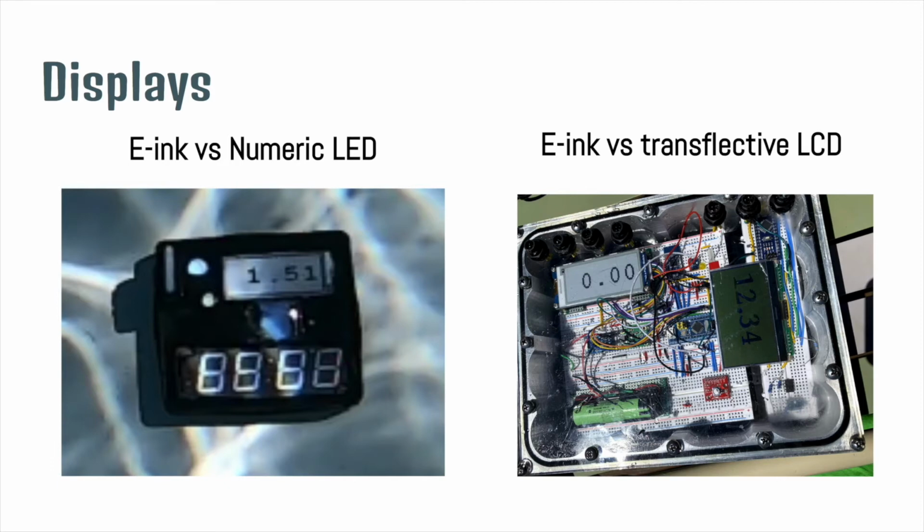The code for the ink module is developed based on Arduino libraries. We programmed it to have a refresh rate of 20 seconds. In our design, we implemented a sleep mode to power off the display when not in use in order to preserve the ink display functionality and power.